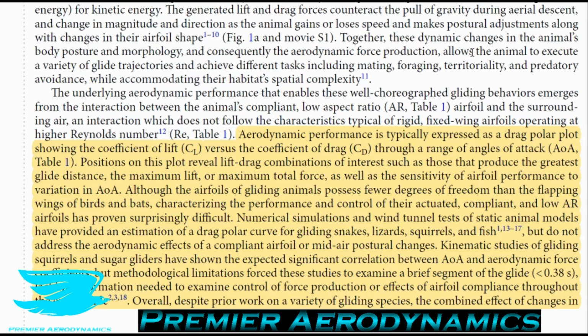It's not actually at a 3-degree angle of attack in reality, because you have flow being redirected around the rest of the fuselage and the wingtip vortices, etc. That will change how the flow that's actually hitting the wings hits the wings. So you can actually have an effective angle of attack of maybe 2 degrees, 4 degrees, 5 degrees, whatever.